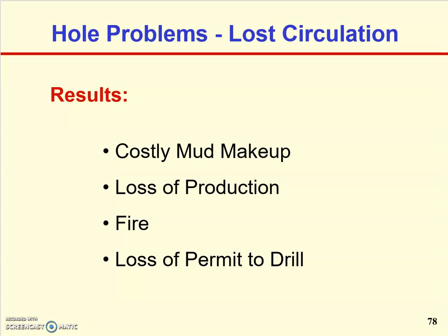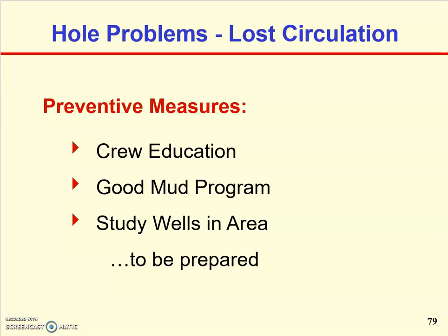So you need to be careful about that, and in order to be careful, you need to take preventive measures, and these are educating the crews on the surface about the drilling fluid properties, what properties you should have, and also detect these lost circulations quickly, have a good mud program, and study the other wells in the area to be prepared for the formations that might have characteristics like that.